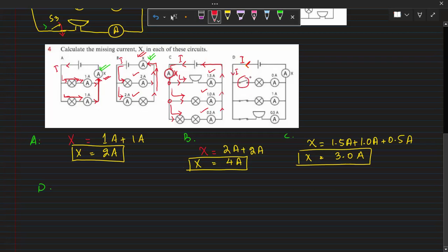Therefore, we won't get any current here, and you can see the ammeter shows zero reading because no current is entering here. Therefore, 0 ampere will be there, right? Now the current will continue to move on. It enters at this point, and that's going to be 1 ampere. Okay, and the remaining current will enter at this point, passing through the buzzer, and it shows 0.5 ampere.